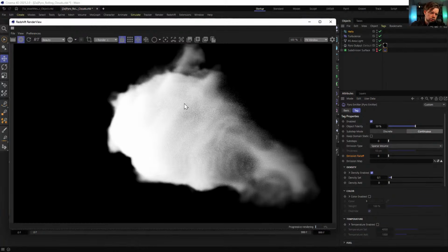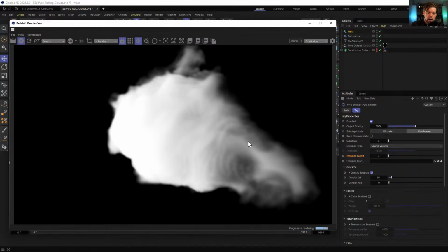Oh, actually, yeah, it's not showing up in the render because essentially everything is, even though I kept on saying how dense the density is here, we do have to see, I don't know how many we're seeing through here, but right here, maybe we're looking through like 20 different voxels worth of volume. And so each one's only contributing like 10%. So we're not really seeing much in the way of stepping here, maybe a little bit. And to me, the best way to get rid of that is just increase your resolution. If you double the number of steps, then you'll halve the amount of banding you're seeing.